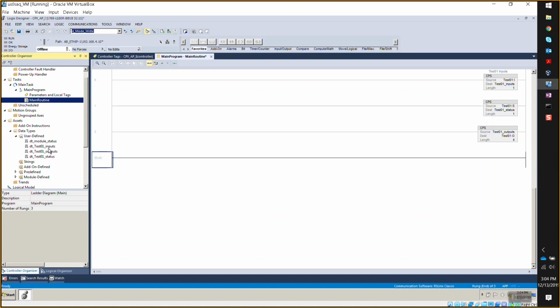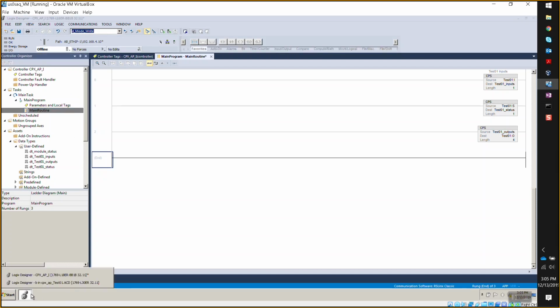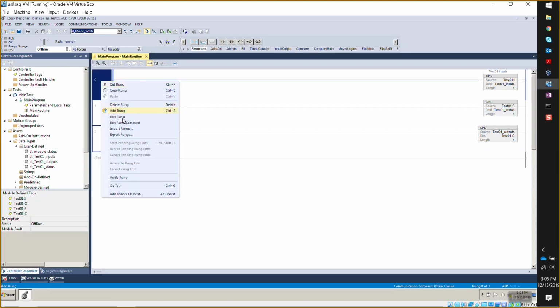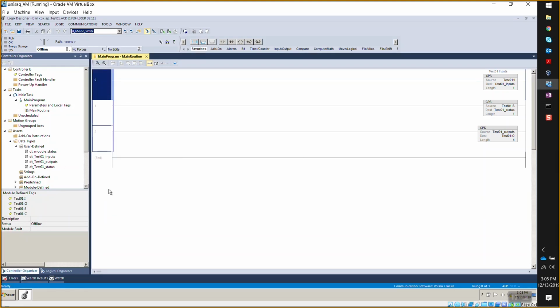Yeah, that was going to be my next question. Like, how do I export the UDTs and bring them over here? But it's already done. It's very important to do it this way. Do not copy and paste over the UDTs. It will not work right. So it's important that you not only go and do something like, oh, just right click and copy rungs, and then bring it over. Do that. You have to export it and import it. Gotcha. Okay.